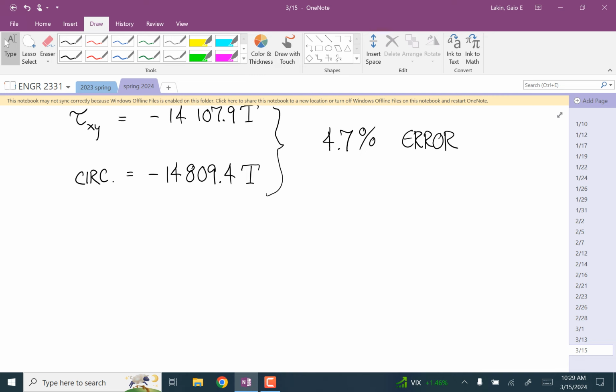Use the rotation matrix to put it in your regular system. And once you have your stress due to tension, bending moment, shear force, and torsion, all expressed in your desired coordinate system, then you finally just add them up and that's your stress tensor.